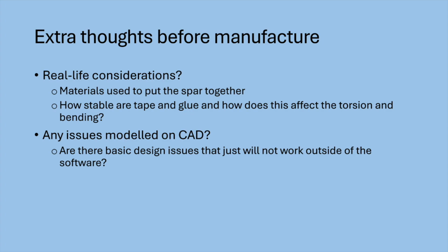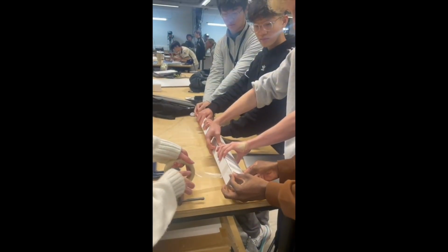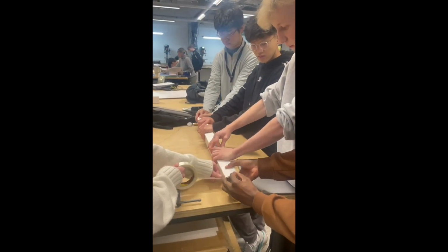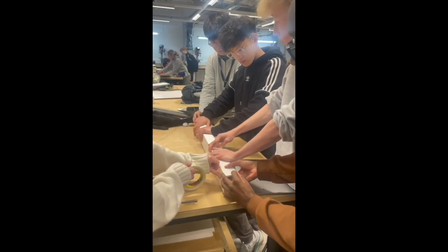At this stage, real-world conditions, which might have been ignored in the previous stage to simplify analysis, must be considered. For the wing design, the spar was made from laser-cut foam board and assembled with hot glue, whose weight was ignored during analysis, while a sleeve to hold it in place when clamped was designed in SolidWorks and 3D printed.